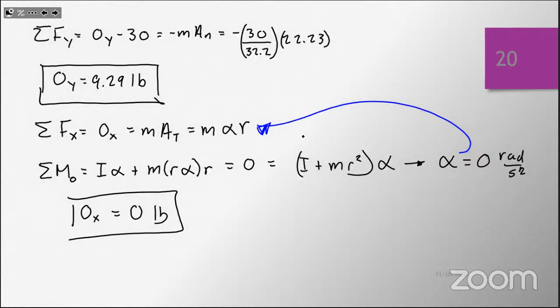I is the mass moment of inertia, right? And that's a lookup from the table, or you use k squared times mass to get it. In this case, we use the table, even though I didn't show you the table. A beam is a very common one that's 1/12 m l squared. If you need one for an exam, you'll be given it, or k, or you'll be given a table to look at, one of those options.